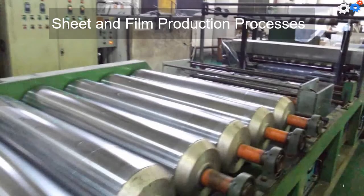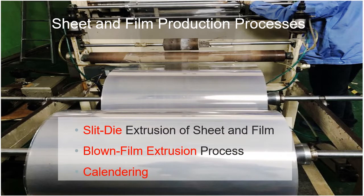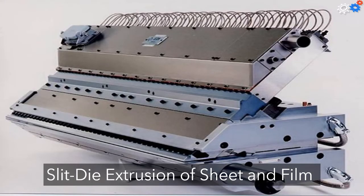The most widely used processes are continuous high production operations. These processes include the slit die extrusion of sheet and film, the blown film extrusion process, and calendering. Slit die extrusion of sheet and film uses a narrow slit die opening to produce a plastic sheet and film by conventional extrusion.